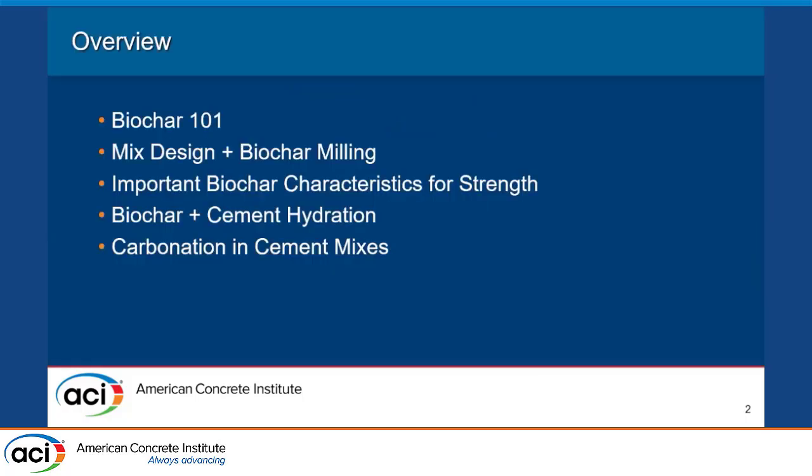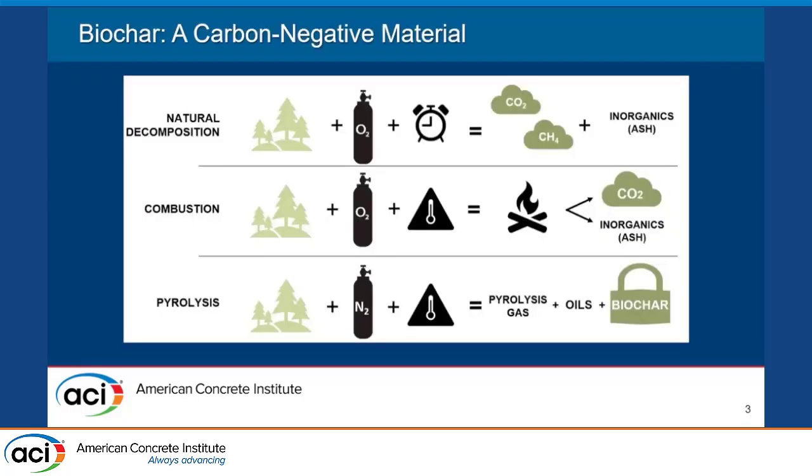Quick overview, I'm going to be talking about a little bit of Biochar 101. Probably going to cut this part because we have kind of talked about it a little bit. Then I'll discuss our mix design and how we mill the biochar before integration. And then I will discuss the model that Seth nicely introduced for me for determining what the important characteristics are for strength development. And then I'm going to talk a little bit about biochar and cement hydration and some of the carbonation that we see in cement mixes.